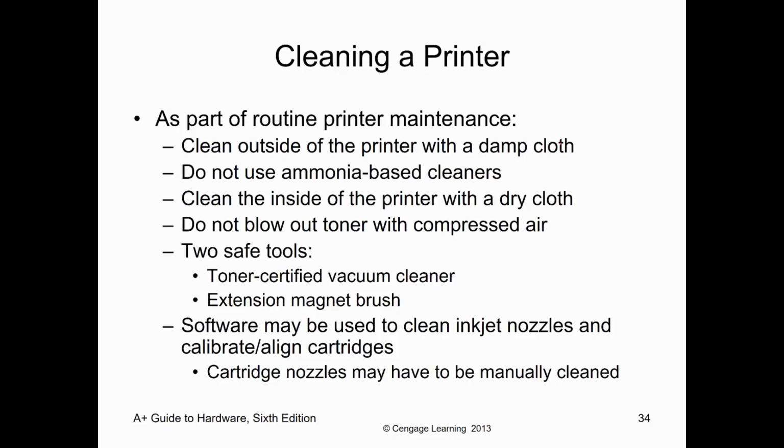If we are looking at a traditional inkjet printer, you're going to clean the outside of the printer with a damp cloth. Not super wet, but just damp. We're not going to use anything with ammonia. Normally, distilled water is going to be the best. We are not to blow out toner with compressed air. We want to make sure we're doing this safely. Maybe use a toner vacuum.